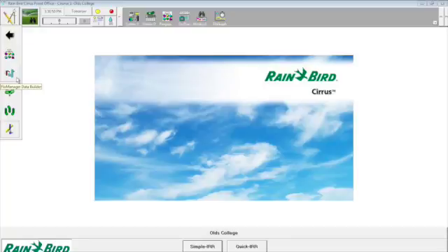When using the RainBird software, using the map will generally be easier than entering data manually, as there will be multiple branches, flow zones, and stations assigned to the flow zones. Any information entered on the map will also auto-populate the tables in the station details area. For the purpose of this tutorial, we will be using the 15th hole at the Canal at Delacour golf course.